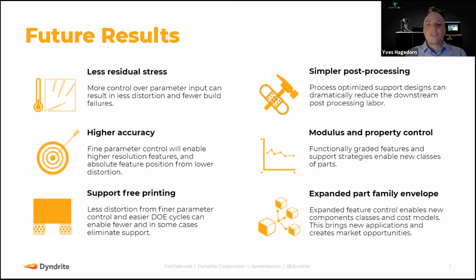Ooh, that's difficult because there is a lot to do. Well, in toolpathing, what is still bothering me is this STL format, and we apply a scan head based technology, right? And the CLI format, so to say, which we use, are straight lines, which you pointed out beforehand. So what I would love to see is basically, if you want to scan a cylinder, that you get rid of those straight lines connected, with some little delays to make sure you get a sort of tessellated cylinder object, so to say.